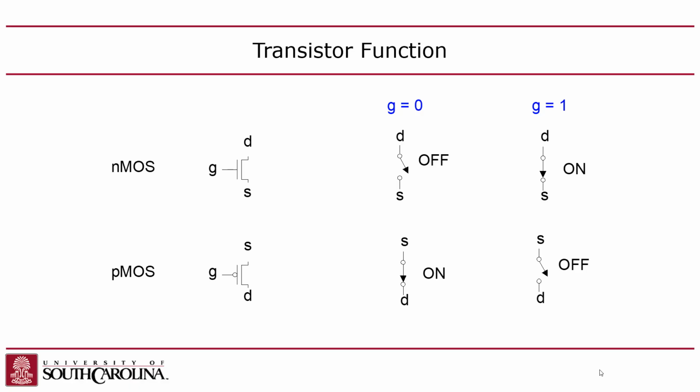Now you might say, wait a minute, I thought you said it has to be negative. Yes, because in the PMOS, logic 0 actually creates a negative voltage on the gate, because the body terminal of this guy is actually 1, is VDD. So if you put a 0 here, you get a negative voltage. But for the purpose of digital logic, you just say this is a 0.